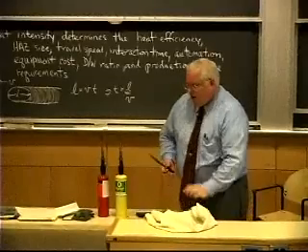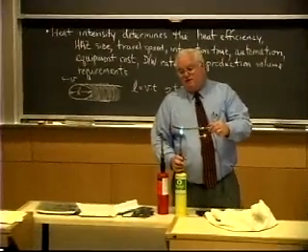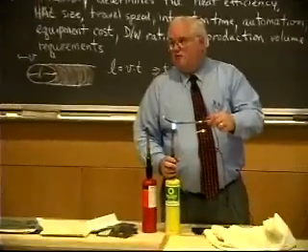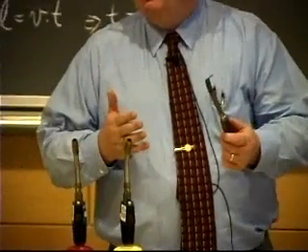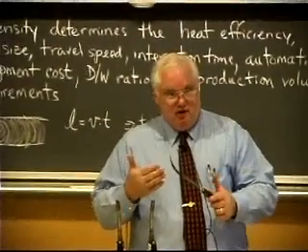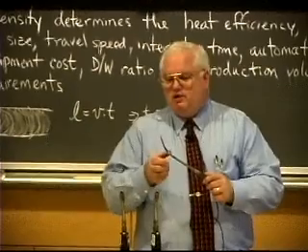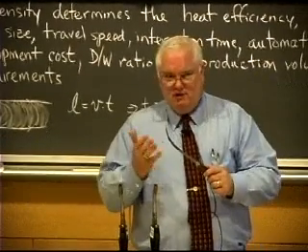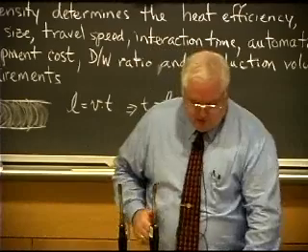So if I cool it off now, I can heat it from either side, and it should still bend in the same direction because it's based on the material properties, not the side that I'm heating. Okay, it's not that one side's good. Certainly, if I heated one side faster than the other, something would bend, even if it was not monolithic material, if I had a temperature gradient. But this is thin enough. There's not any substantial temperature gradient. This is because it's a bimetallic strip, and it always curves in the same direction.